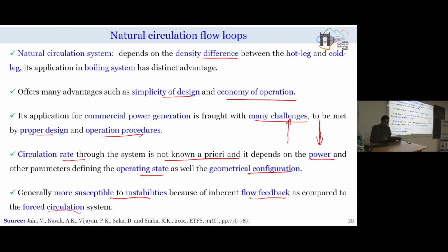Let us assume that at some point of time, one vapor bubble has started forming. This vapor bubble will keep on growing, and it may so happen that if growth of the bubble is rapid, it will entirely block the path. If it is entirely blocking the path, then immediately the flow behind this will be stopped unless some next disturbance comes to initiate the flow.